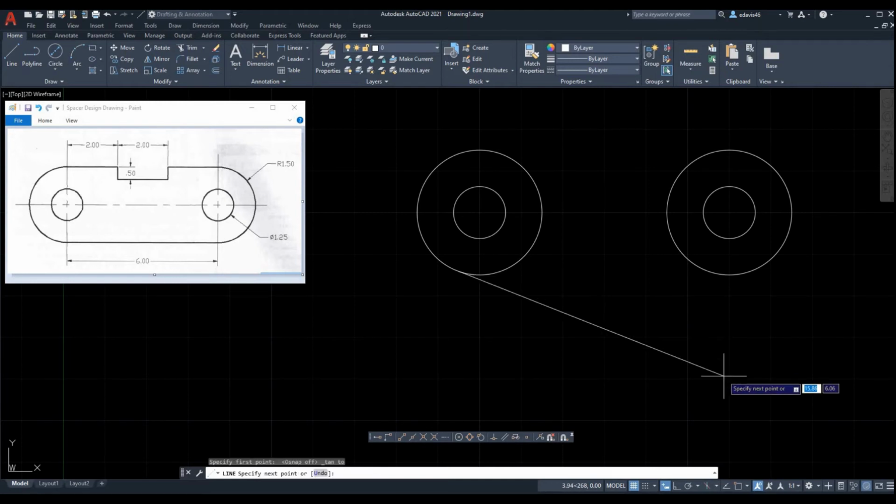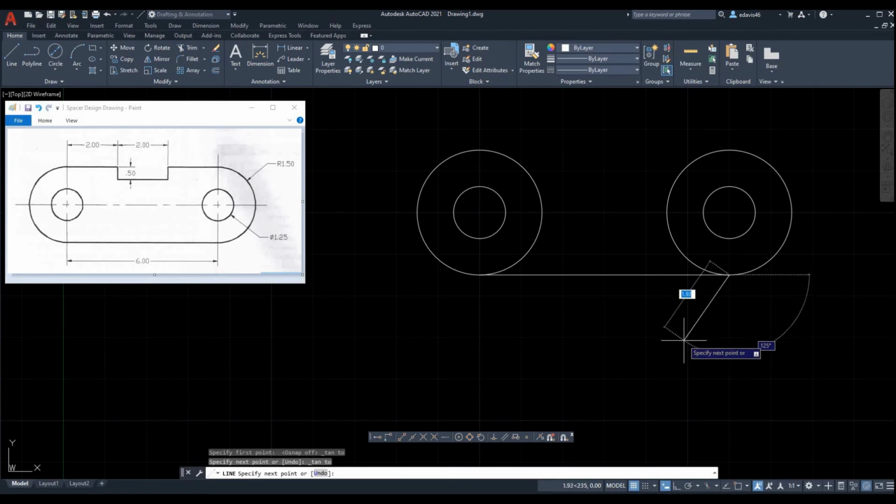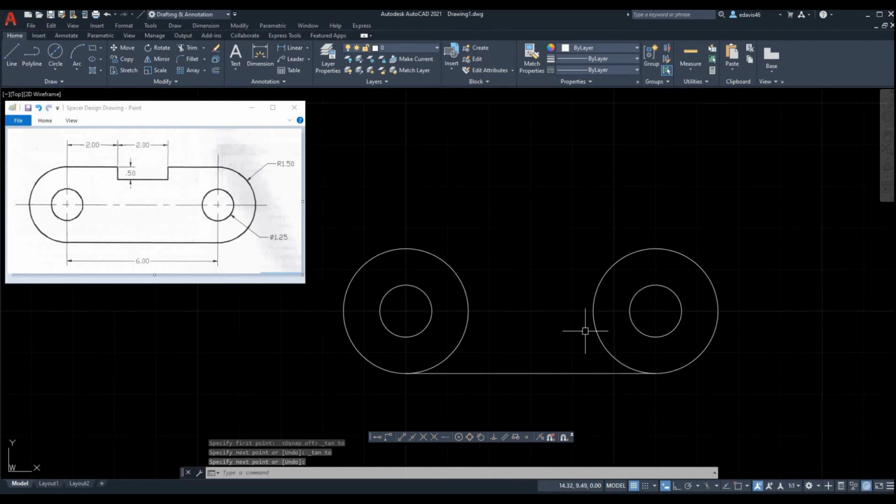But we'll go ahead and start our line. Kind of drags around there. We'll hit that snap to tangent again, go over to this circle, and then now we have a perfect little line there. Scrolling back up, for the top section, I'm going to draw 3 separate 2-unit increment lines going all the way across, and we'll see why we're going to do that in a second.